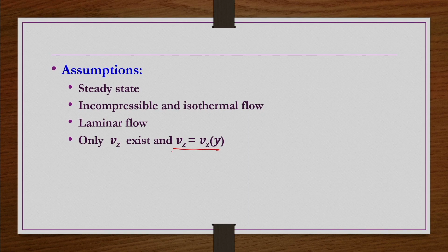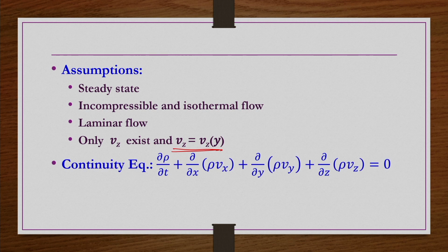Within that thin layer of the material, how the velocity profile varies. So, for such a thin layer of material flowing down, only one component is going to be predominant, other components are going to be 0. That is, in the vertical direction or in the x direction, we are not going to have any velocity. So, Vz is only existing, Vx, Vy are going to be 0.